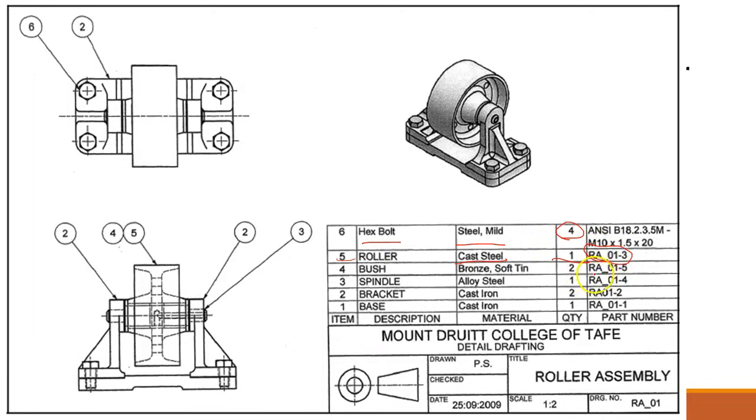And you can see that all of these components have their own drawing with all of their separate dimensions and features. But just from this one drawing, you're able to see exactly how this component is assembled and what all the parts are together and what they're made from. So this is a really important drawing because you could actually use this to order and buy more or get more manufactured and still know how to assemble it together. So again, this communicates all the way from the design, in this case all the way to the assembly process.